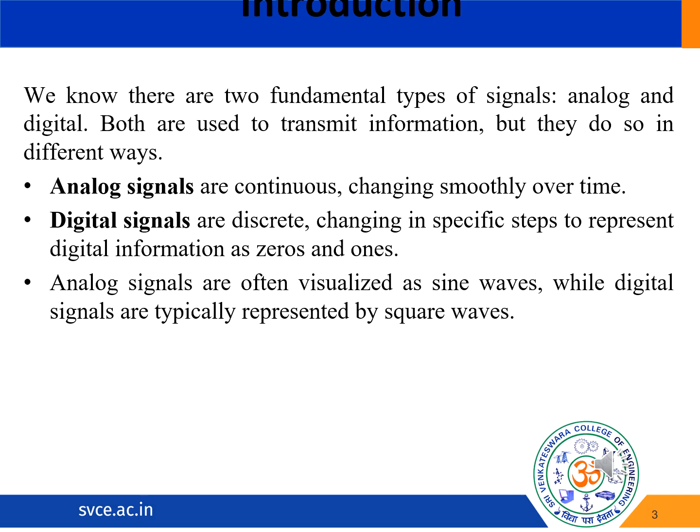So now we have learned about on resistance, and the next thing is off resistance. So this is the resistance between the input and output terminals when the switch is off. So you have to identify when the switch is on, when the switch is off. When the switch is on, it is on resistance. When the switch is off, it is off resistance. So typically when you consider off resistance, it is in the mega ohms or giga ohms range.